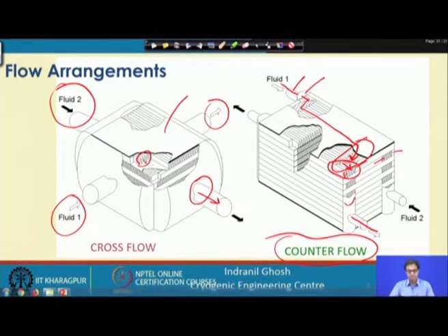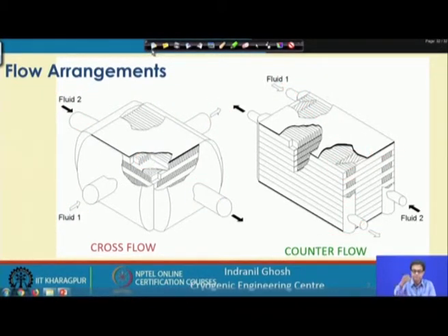So, we have a very stringent requirement, particularly in terms of the brazed aluminum plate fin heat exchanger, as we have discussed earlier, because the solidus and the liquidus temperatures of aluminum are very close, and we need a very stringent temperature control in the furnace or in the dip brazing. I mean, we will discuss that in the later slides.